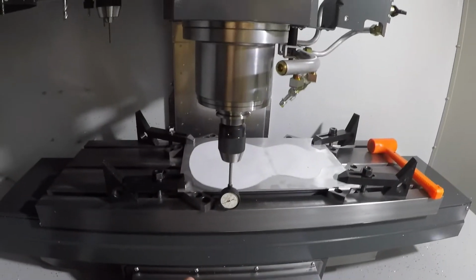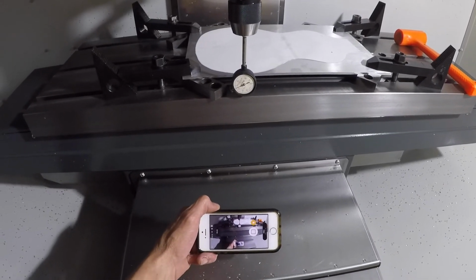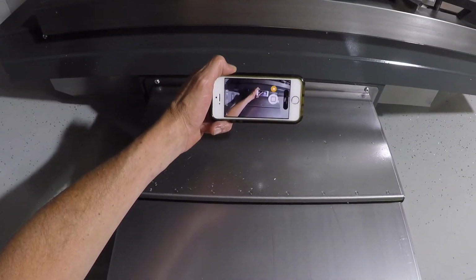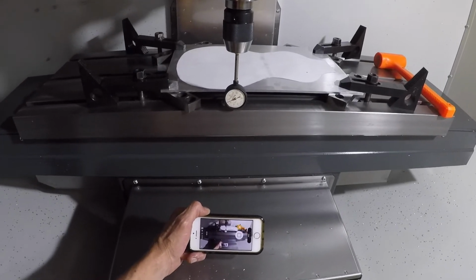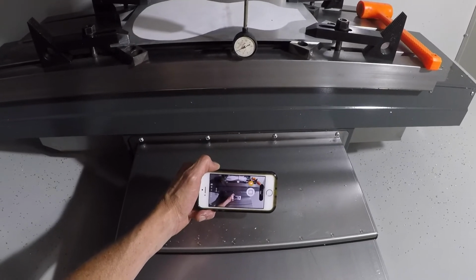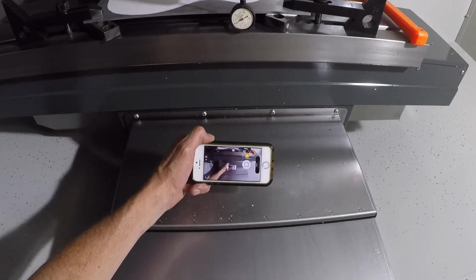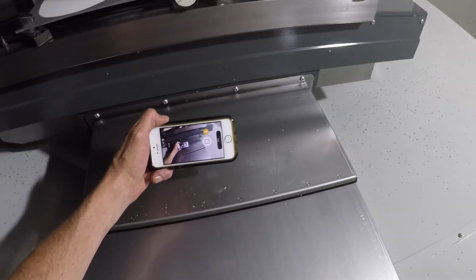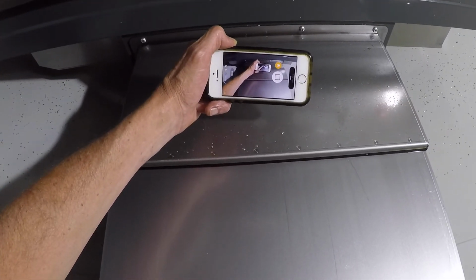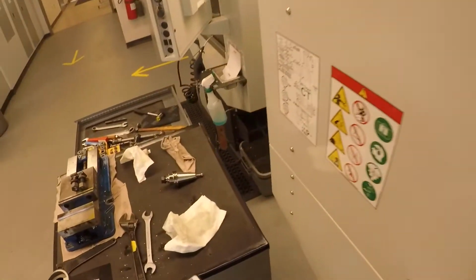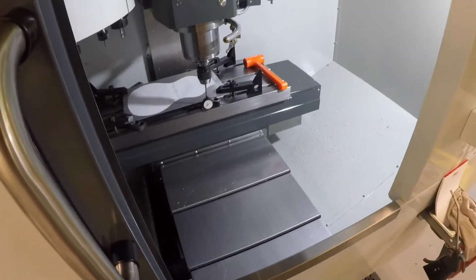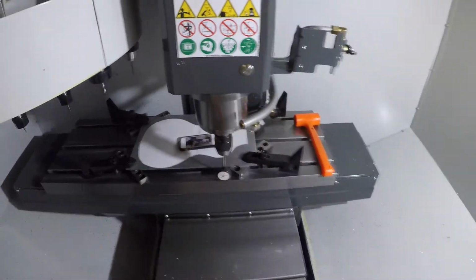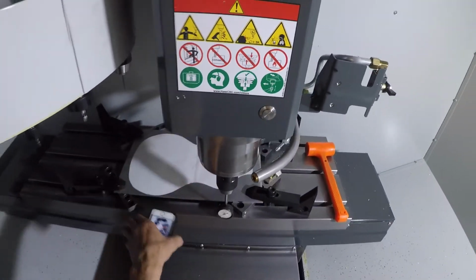So that indicator there says 35, 36. I'm gonna call that 36. It's a little below it, but it says 36. And as I move X, the needle is going off of surface imperfection. All right, there it is. So that says 33. So I'm 3 thousandths out. But you can see I can tap on it, and it was about 1 or 2 thousandths out before, and then after I tightened it, it moved on me. All right, but we're good.